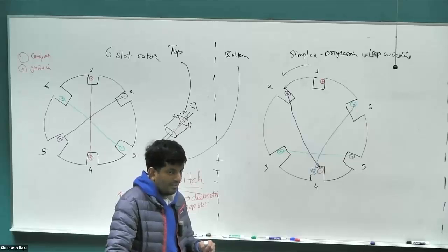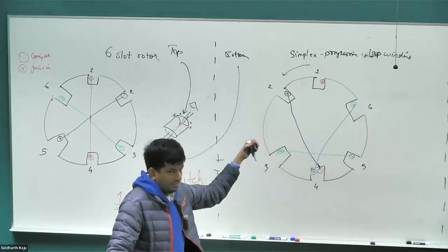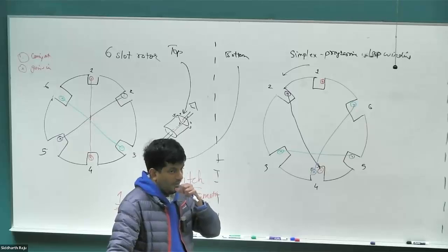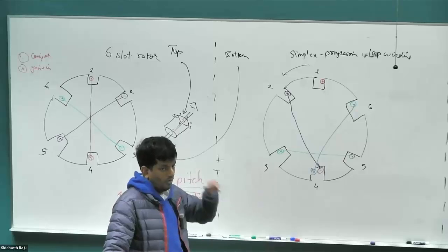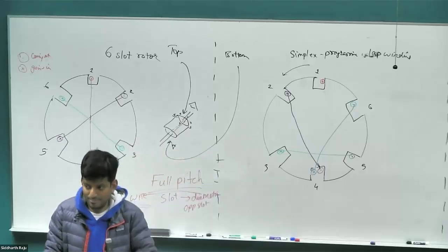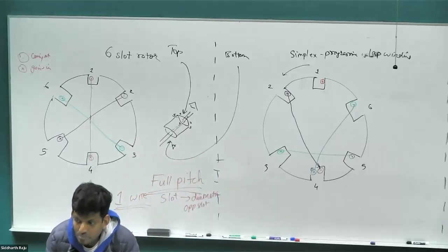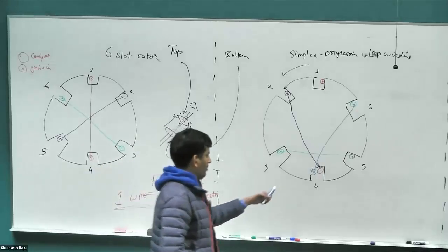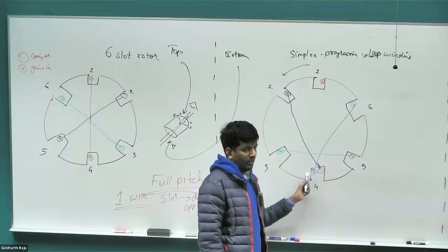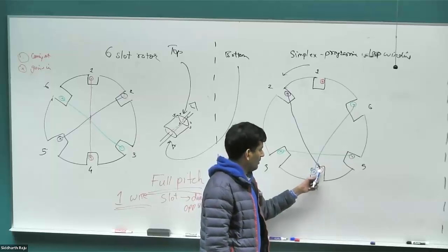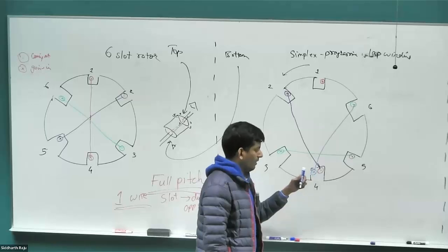Happening at different times. These are all conductors present in the motor, right? All of them are going to carry current through them. And we said it's a single wire that's going through all of those. Yep. Depends on how you wire it at the commutator. Perfect. So it depends on which direction the current goes. This is just the direction of the conductor. This is not indicative of the direction of the current. So this is a conductor that's coming out of the board. This is a conductor going into the board.